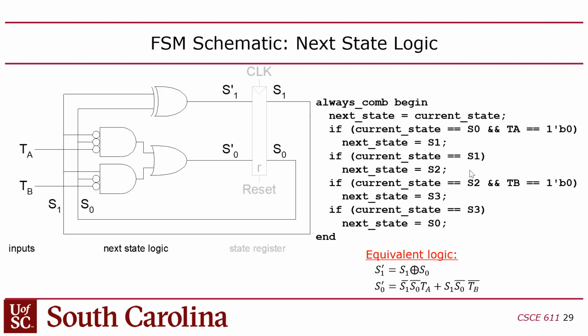And then the output of that register is the current state. So this thing is the clocked logic, and these gates here are the next state logic. You guys with me? Obviously, you don't have to build it, you're just writing this and hoping that it's going to synthesize into the corresponding hardware.